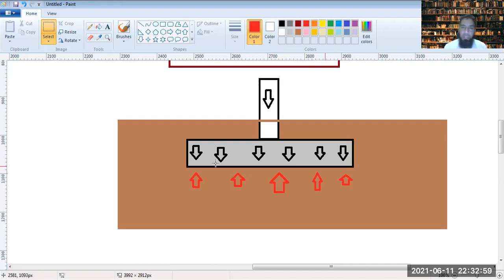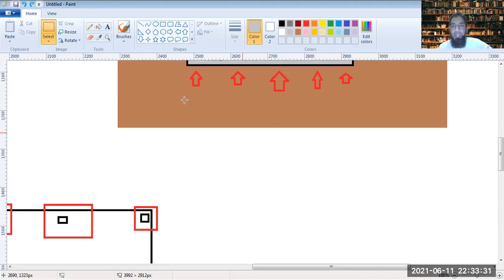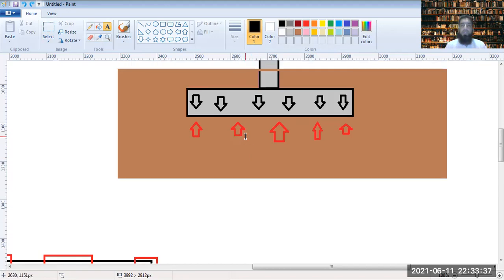So a rigid construction of this footing is the first thing that you require while you are designing this column footing. Thereby, we are assuming that the distribution of the pressure from the soil is even, uniform throughout the footing. This is the first approximation, not an assumption. The pressure reactions from the soil to the footing are uniform, and they do not vary.